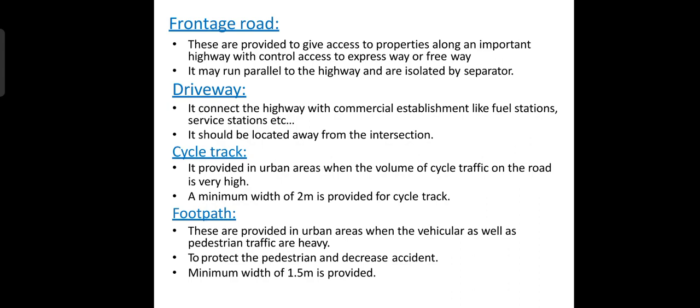Frontage road. These are provided to give access to properties along an important highway with controlled access, such as an expressway or freeway. It may run parallel to the highway and is isolated by a separator. Driveway. It connects the highway with commercial establishments like fuel stations, service stations, etc. It should be located away from the intersection.